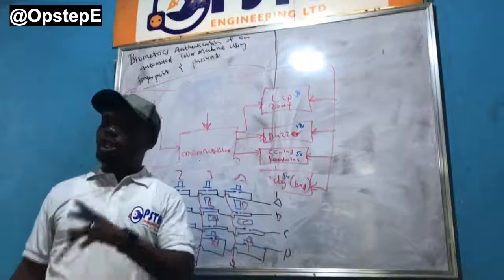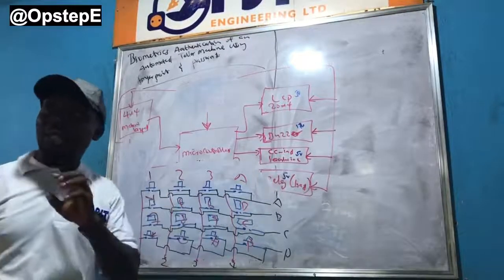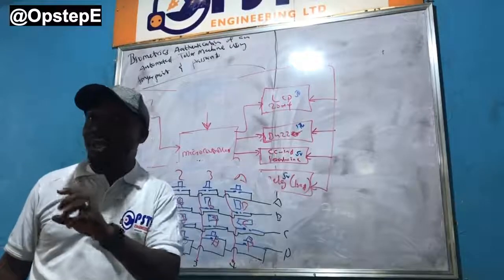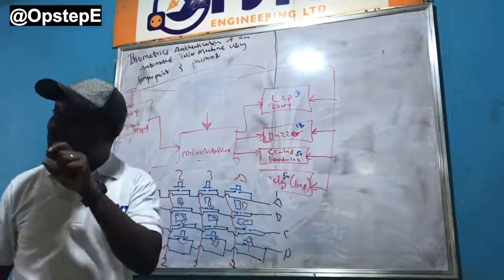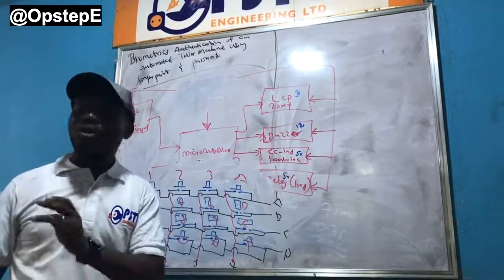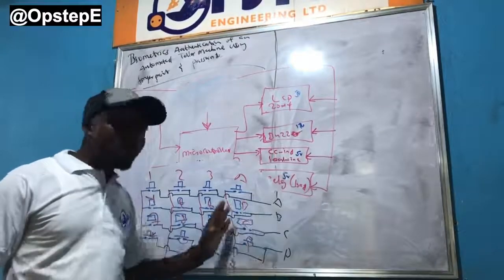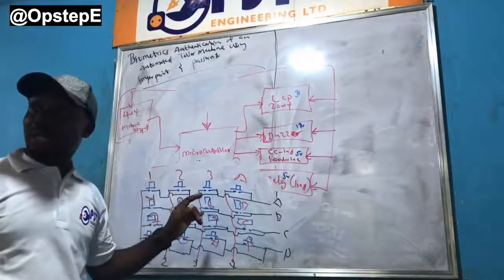You get it? If you find a keypad, a Matrix keypad for that matter, connected to any other pin other than port B on any given microcontroller, there will be at least 4 pull-up resistors. Because it has to act as what? As activator. So that it is low when the button is pressed, and it does what?